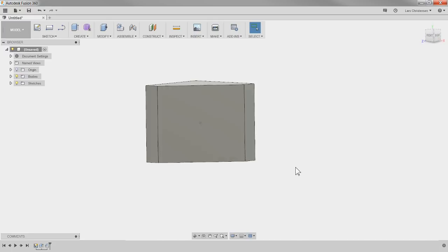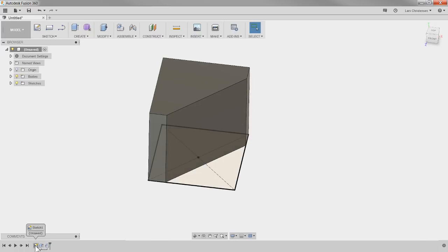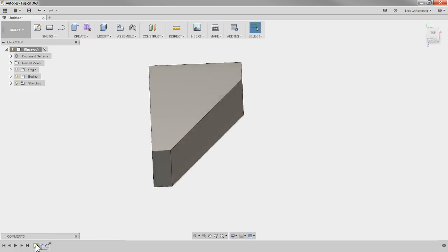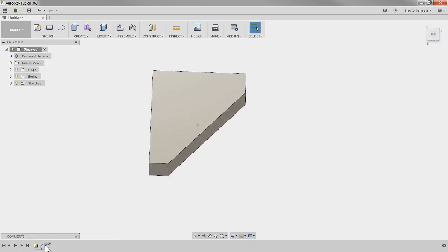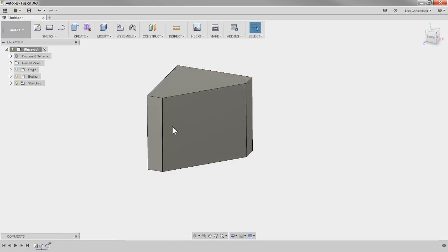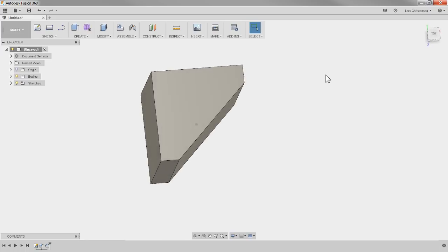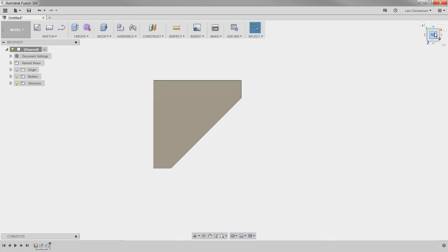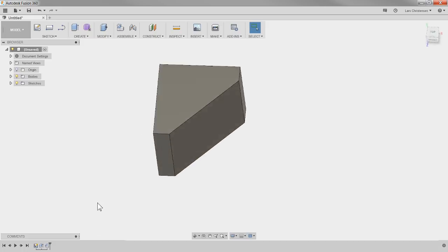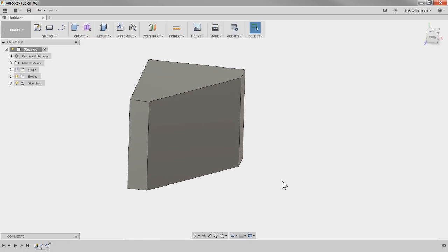Quick question to you guys. If you guys saw how I just modeled this one up, a rectangular sketch, a square sketch, extrude it up, and then use the chamfer tool to put this flat on. If you had ever had to model something up that looks like this, would you have done that, or would you have started creating a line, extruded it up? That's probably what I would have done. I wouldn't have done it with the chamfer tool. So, just a neat little teaser. Just think about some of these tools in there that maybe could help you design a little faster.